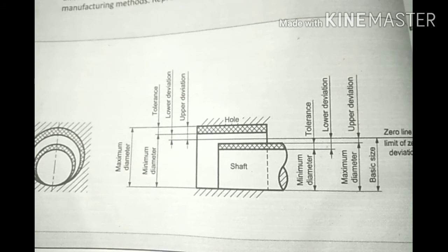in the drawing. Such information like material to be used, dimensions and geometrical tolerances, surface finish required, machining symbol. So the drawing which contains material, geometric tolerances, machining symbols, surface finish required, those drawings are called production drawing.